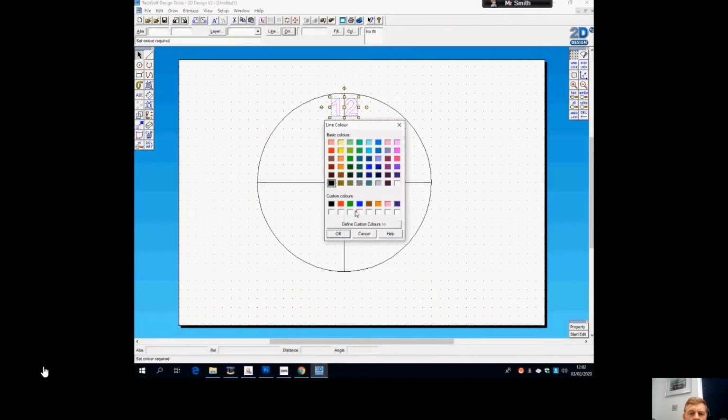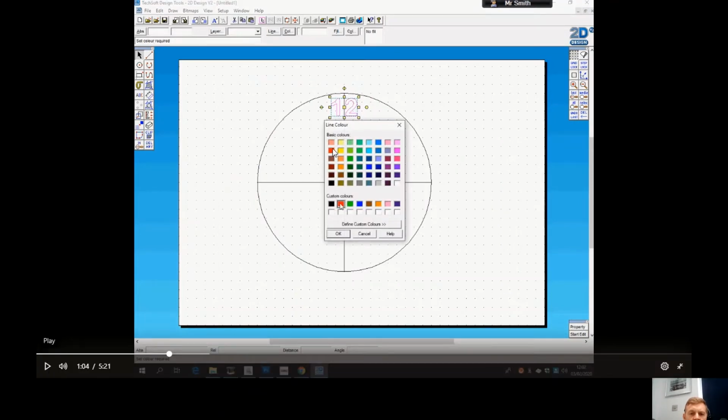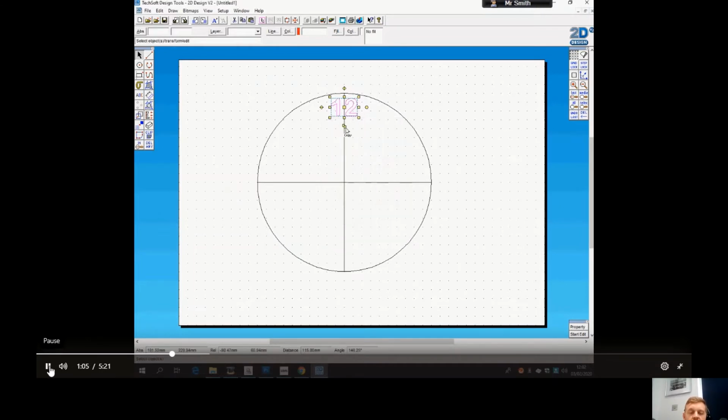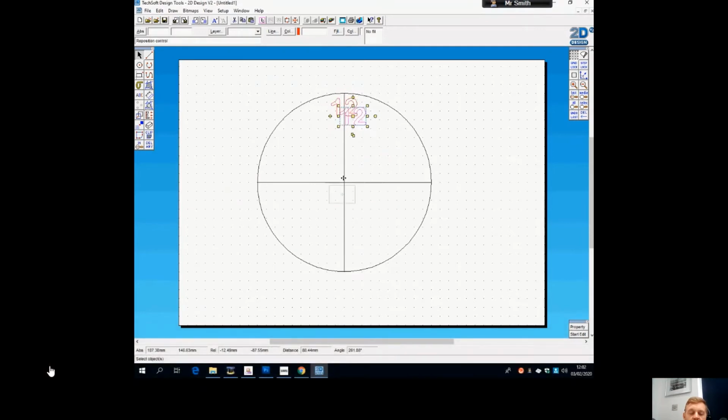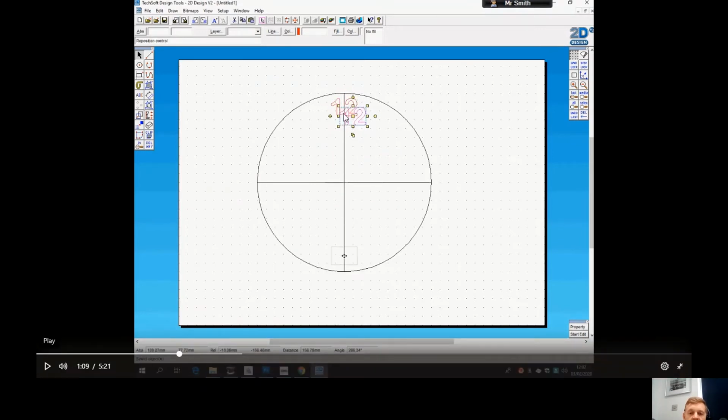There you go. Now, if I want to engrave, which means just burn the surface of the material I'm cutting the clock out of, I'm going to change it to red. Some people have red as cut and black as engraved. It doesn't really matter particularly, but in this case I've always done red as engraved. If you click on the basic color red, I've chosen that one, and then click OK, it will change the outline to red, and it will engrave it.